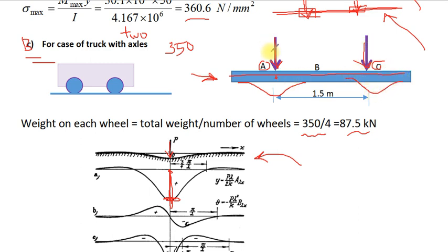But because we have two forces, we don't know, maybe the deflection in the zone between the two forces is greater than under the load at point A or under the load at point C. So we have to take another solution of computing the deflection at point B, and we are not sure that the maximum deflection is at B; it may be between B and A or B and C. So therefore we have two choices now.